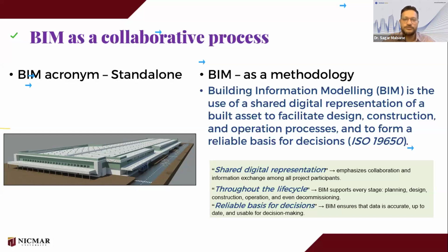But if you really want to be very formal about BIM utilization, if you really want to achieve that ultimate goal of delivering projects super efficiently, then you should look at BIM as a method. And as part of that method, you have to follow the complete mechanism of how to use BIM on a project. It involves three stages: model authoring, which is object-based modeling; then model-based collaboration, where people will share the model; and then network-based integration, meaning through a common platform, participants will come together and work on a common project. Okay.